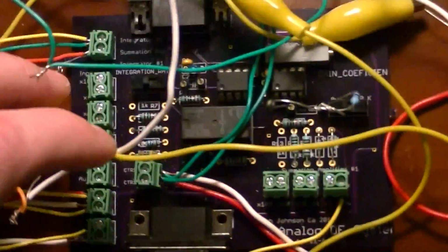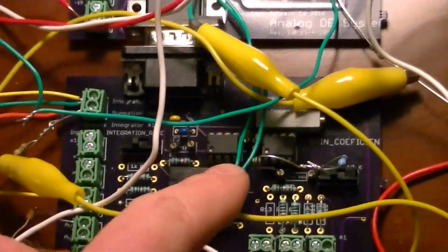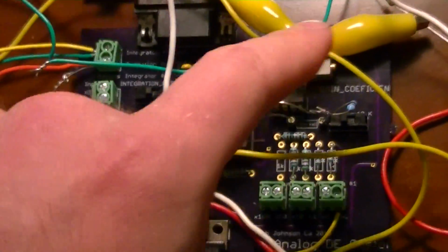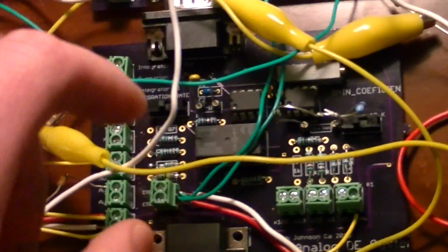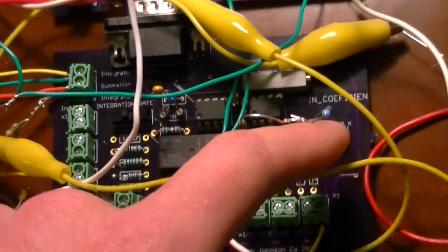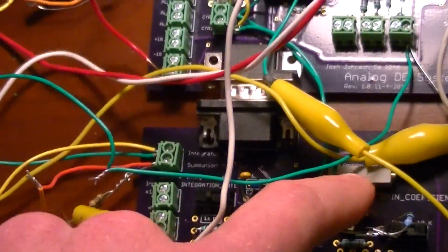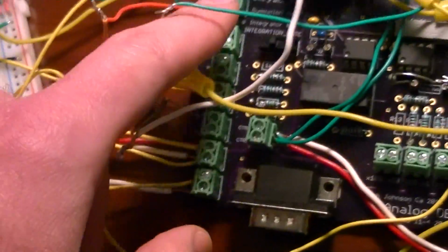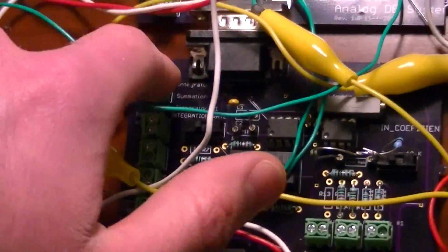Each one, like this one here, can perform one integration with this chip and this network of components, and one summation with this network here. You can change the capacitor with this switch to change the rate. You can change the element in feedback with the summation amplifier here. This sets the initial condition, and these are the inputs for the integrator and the input for the summation amplifier. The output for both is here.